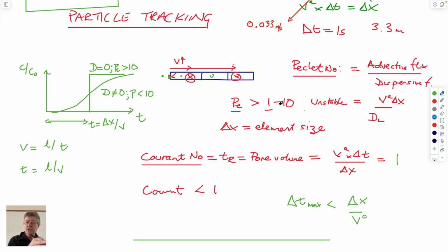In other words, a static mesh, and the contaminant washes through that static mesh, so it sees it going past, as opposed to Lagrangian methods where you attach yourself to a particle and you go downstream and you end up in a location and you count the number of particles at that location. So fundamentally different. One is a static mesh and you watch the fluid or the contaminants travel through that mesh and solve it for the static mesh. Or you attach yourself to a particle and you move down from node to node to node, which is what we're talking about in terms of particle tracking.